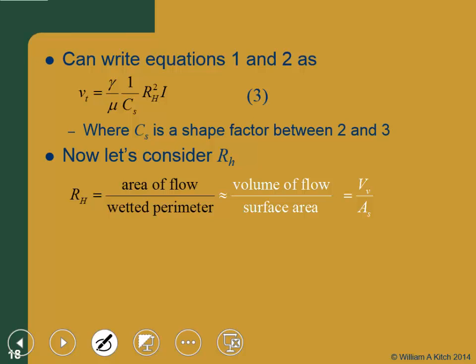We're going to call this the wetted perimeter. Okay, is that the total surface area? Yeah, the total surface area. So I have a sample of soil that I'm interested in. I have the total volume of that soil and the surface area of all the particles within that, right? I should say that we're talking about saturated flow, so the water's going to be in contact with the surface area of all the particles. I'm missing the contact area where they touch and there's no flow.